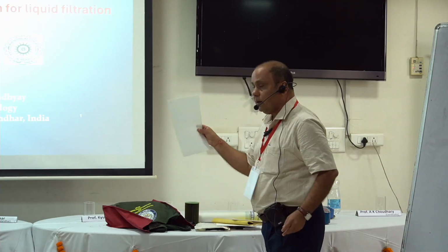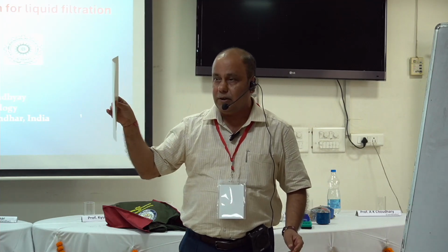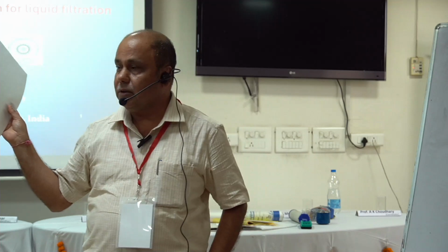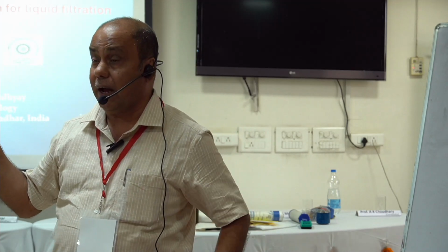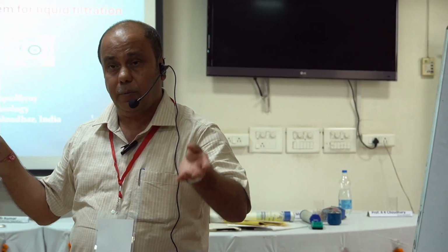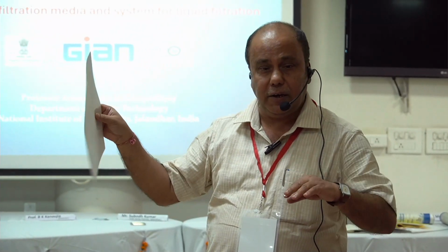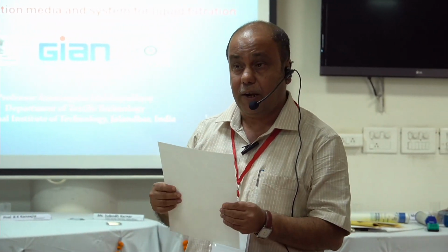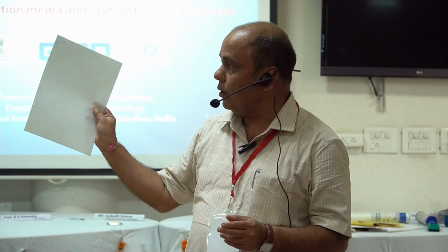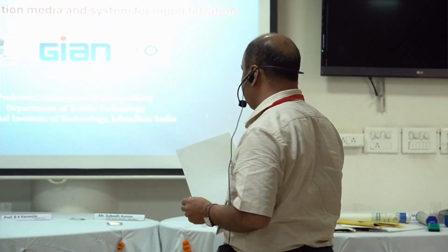Now this is another liquid filter. If you see, it is a spun bonded material. Earlier was the needle punch, and it is highly consolidated. Needle punch followed by spun lacing technique. It is a spun bonded technique, very stiff, very compact. Okay, so this can work for liquid filtration for certain applications.